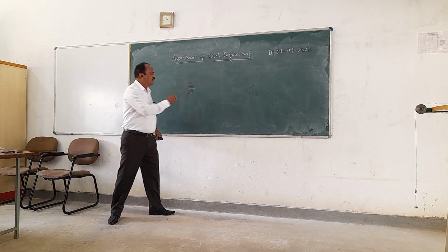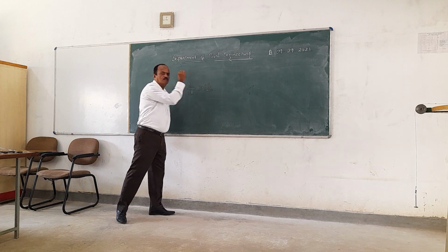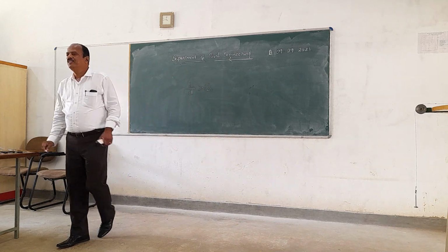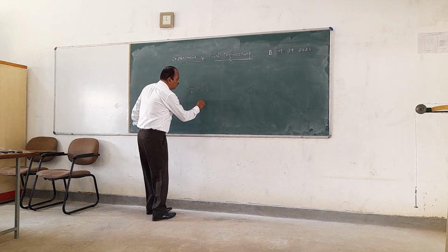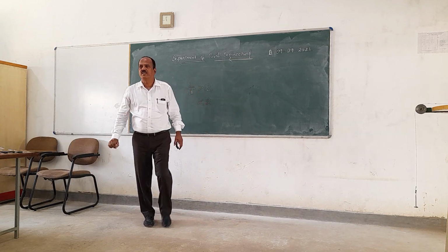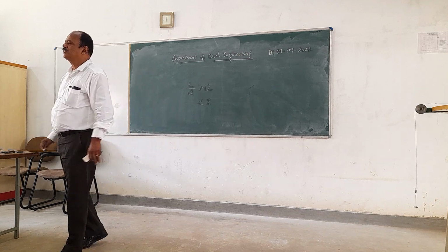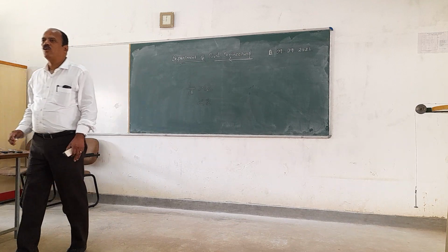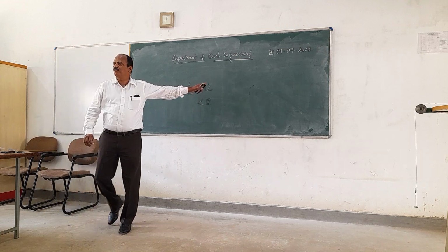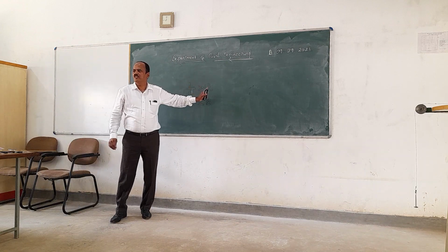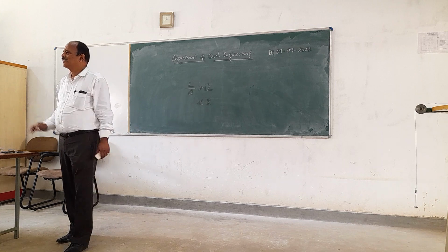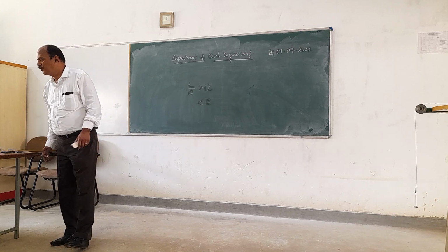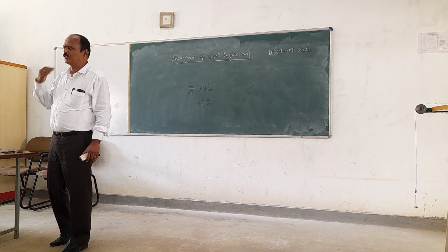If this ratio is greater than 12, then you are going to call that particular column a long one. If that ratio is less than 12, then you are going to call it a short column. This is the main basis upon which we differentiate between a long column and a short column, mainly depending on this L by D ratio. Anything in between, in general, we call an intermediate column. That we have already come across.